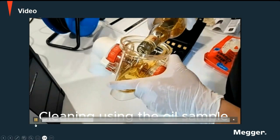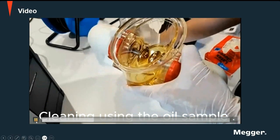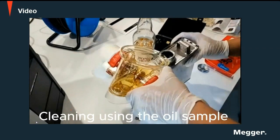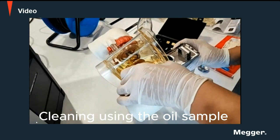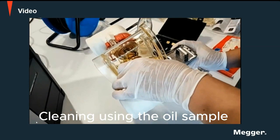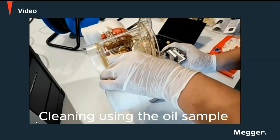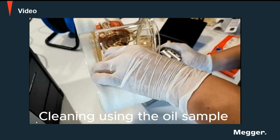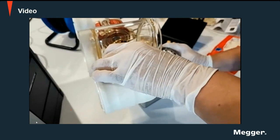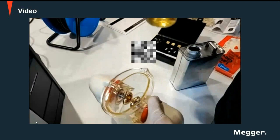Okay, this is for the cleaning, and you have to rinse carefully and slowly, so do not create any bubbles or let air go inside that vessel. Any part of the vessel that will be touched by or in contact with the insulating oil, you need to rinse it. Even the lid, the impeller and the electrode, everything.